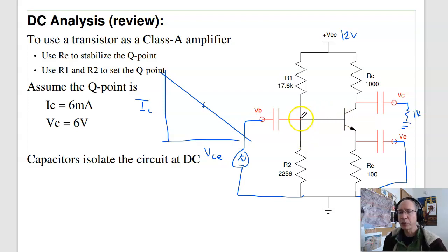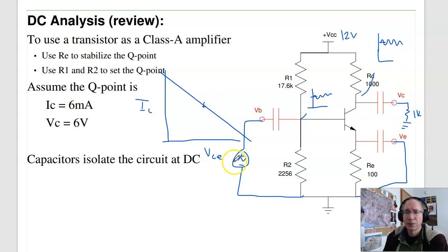If you look at all the voltages on the circuit, say right here, we'll have some DC signal. On top of it, I'll have a small AC signal, like 1 millivolt at 1 kilohertz coming in. The output right here at the collector will also have some DC offset, plus it'll have the sine wave, the 1 millivolt, amplified in some way. Come up with a way to model this circuit in terms of the AC characteristics. And that'll be the two-port model, also known as the small signal model. So that's where we're heading.